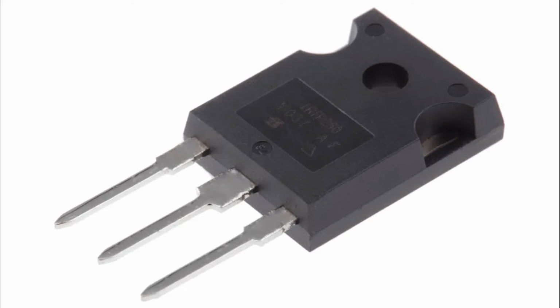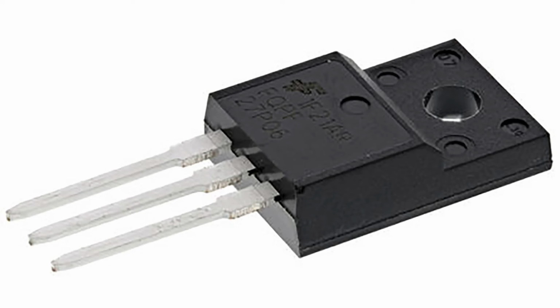7. Simple drive requirements. Description: The voltage-driven nature of MOSFETs means they can be driven by simple voltage levels. Advantage: This simplifies the design of gate drive circuits compared to bipolar junction transistors, BJTs, which require continuous current to remain on. 8. Integrated protection features. Description: Many modern power MOSFETs come with integrated features like avalanche ratings, which provide protection against voltage spikes. Advantage: These integrated features enhance the safety and reliability of circuits, making them easier to implement in complex applications.